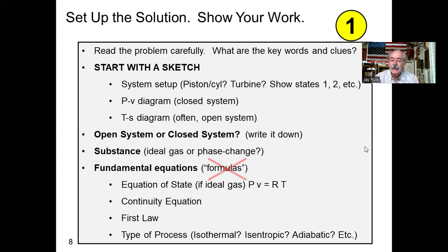So what are examples of the fundamental equations? Well, if you have an ideal gas as your substance, the equation of state is clearly a fundamental equation. P times little v equals RT. There may be others; remember, P times capital V equals mRT, and on. But that's a fundamental statement about an ideal gas. Okay. The continuity equation is a fundamental. More on that in a second. The first law, or conservation of energy, is a fundamental equation. That's where you would start, not just start writing down a specialized formula.